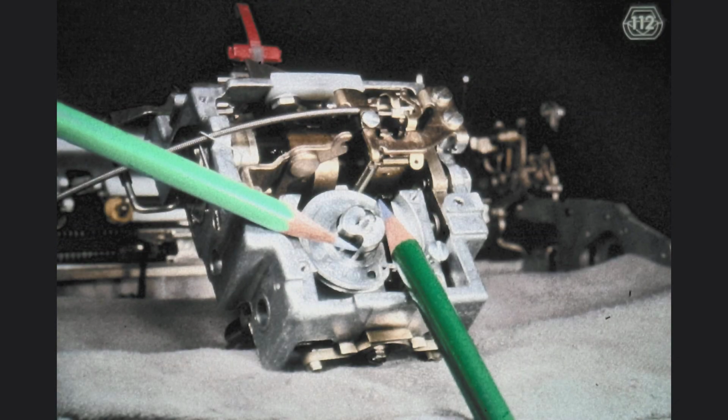When the rotate spring is under tension in a fully assembled machine, the center end of the spring is held by the rotate pulley, and the rotate pulley is held by the rotate tape. The outside end of the spring is held by the spring cage, and the outer rim of the cage is held by the retainer spring indicated by the green pencil. Let us point out once again that this retainer spring is fastened directly onto the rocker frame, and that it functions just like a ratchet pawl, so that through the spring it becomes possible to increase or decrease the rotate spring tension. Thus, we are able to turn the rotate spring cage while the rotate pulley is held stationary by the rotate tape.